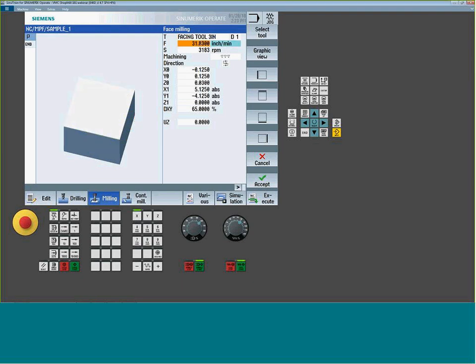So, from our feed rate perspective, just like we saw before, I can select whether I want to be in feed per minute, in this case inches per minute, or I can use the select key with the horseshoe and toggle it to feed per tooth. So the system can actually calculate feed rate for you based on the feed per tooth parameters, and when you get to RPM, you can do RPM, or you can set constant surface feed.